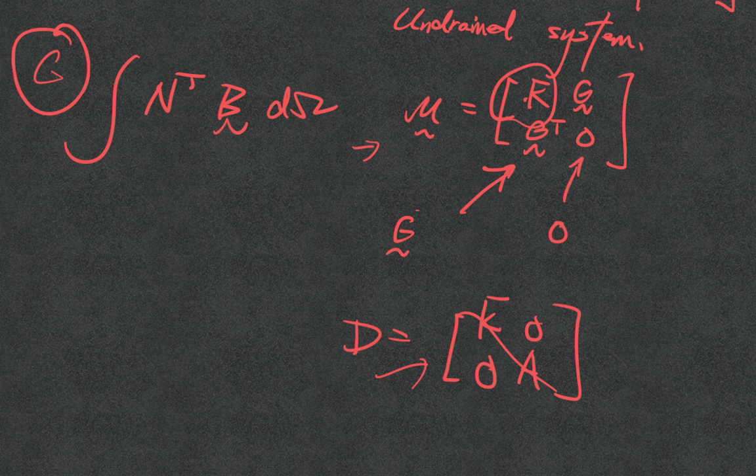Okay, you see what I mean? And you need to actually think about how you are integrating it, what is the space for n, and is the space for n, for the degree of freedom of pressure, compatible with that B matrix that is actually used for the solid? What I mean by compatible is that they give you the full rank, okay?